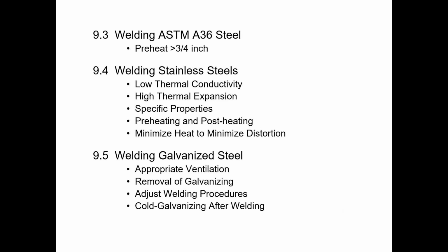With plate and many different types of ASTM standard shapes, HSS tubes, pipes, wide flanges, channels, angles, those types of things, those are typically grade 36, meaning they're 36 KSI steel. So they're slightly lower tensile strength. You can special order those with different grades of steel, but typically, if you haven't special ordered it, it's most likely going to be grade 36.